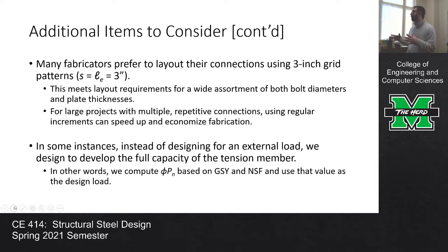So you do still need to know how to customize your connection. Usually whenever I'm trying to rough out an estimate or rough out some plate sizes, I'll go with 3-inch spacing in my head just because I know that's about what it'll be, and I can tighten it up later if I need. So that's just something to keep in mind for the real world as well.